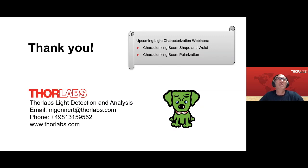When we have the real dark current, the zero biased mode reduces it to almost zero. In biased mode, it can cause problems, and there I would recommend balanced detection, where you balance out this dark current noise. Okay.